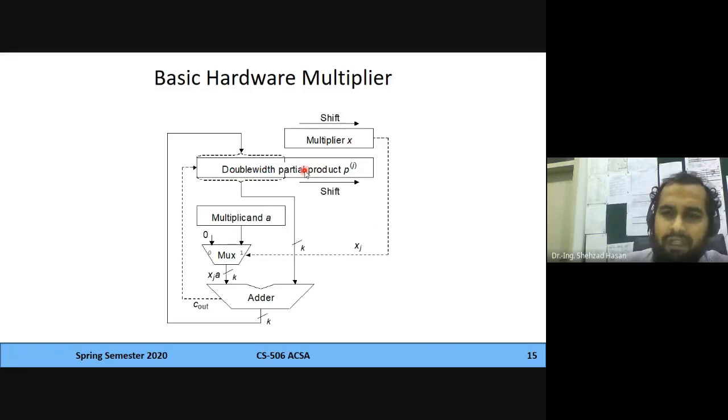So if we go for regularity, we go for k-bits. So we have got k, 2k, and k. If you talk about the number of k-bit registers, there are 4 k-bit registers. Actually, there are 3 registers: one holding the multiplier, one holding the product, one holding the multiplicand. But the one holding the product is twice the size. Okay, so again, this is a sequential circuit because it's working on a clock, and there are registers which are loading here, so a memory element is involved.